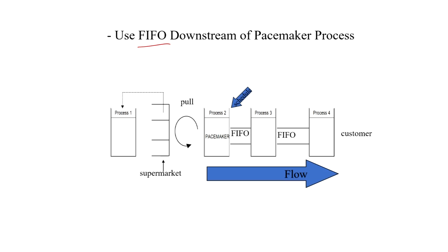There is also the concept of pacemaker. If you have seen value stream mapping, there is one process which is bottleneck in nature. The output of the line is decided by it, as we saw earlier. Suppose there are 10 such processes, some have 10 minutes of cycle, some have 5 minutes, some 15 minutes, 10 minutes, and like that. This is called the bottleneck stage, and the speed of the line is going to be decided by this. So, this is called the pacemaker. The bottleneck stage in a line is called the pacemaker. It will decide the speed of the line.